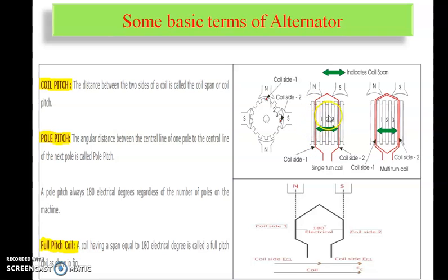Now, and particularly from this, at the end I call this nothing but an end connection. Here I got the end connection, and this part, okay, we are going to connect to the commutator segments. This end of the winding we are going to connect to the commutator, while this end we are going to connect as end connections. Simply, I took one long winding wire and inserted it into these slots, and took it back out from this slot. Okay, so this is nothing but a single turn coil.